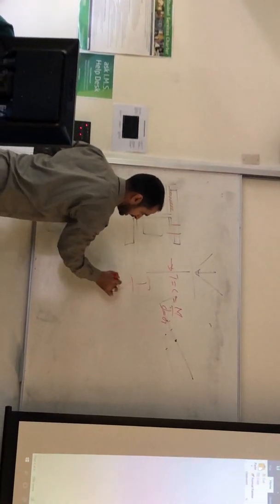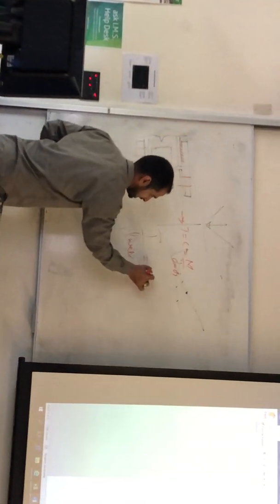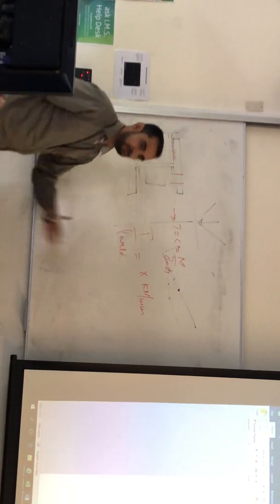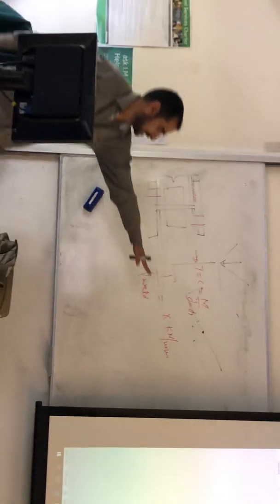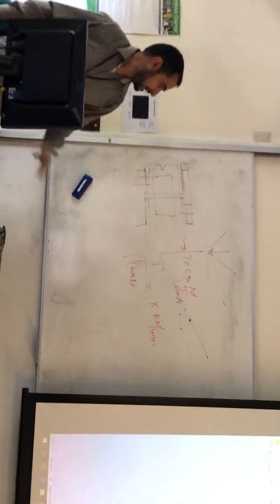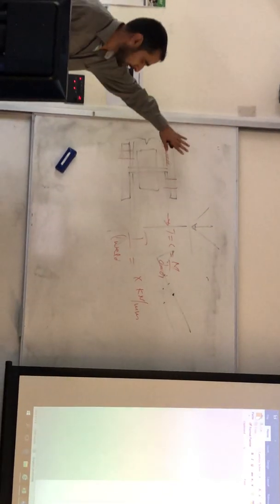So T divided by L weld gives you, let's say, X kilonewton per millimeter. Go and check in the table, easy. Check in the table what weld size has this capacity and pick that weld, that's it, simple. That is all about the flange.